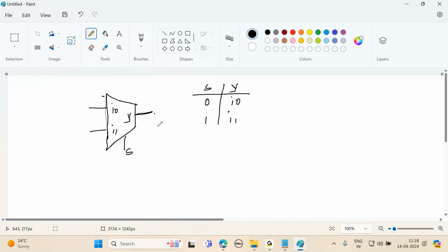Take a D flip flop. If I ask how many of you can define the internal structure, what is the role of the D flip flop? You have a reset pin, Q, and Q bar. Whatever is present on D, it will pass to Q at the positive edge of the clock. You can write the internal structure using gates.